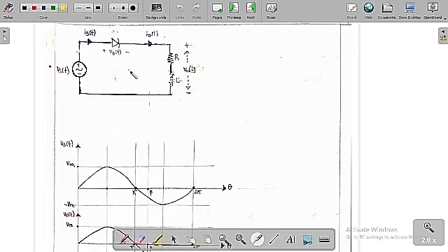So this is some of the important analysis of this circuit. Now we are going to study the RL load. In the first case we studied the R load, then the L load. Now we are going to study the combination of R and L load, and then see the measures of the current and voltage. The source voltage is now Vs of t equal to Vm sin omega t, and this is the load voltage, which is plus minus V naught of t.